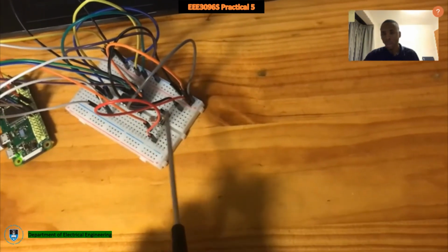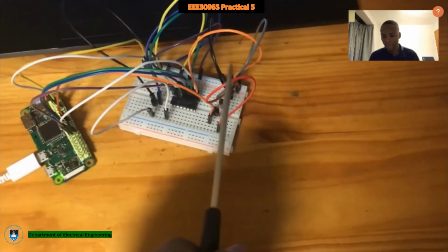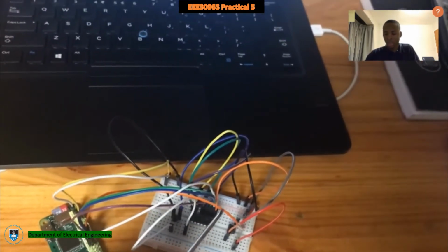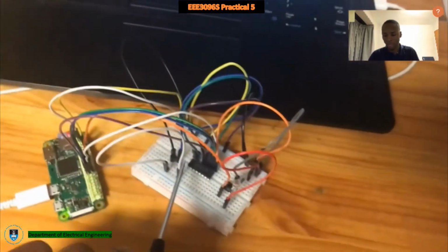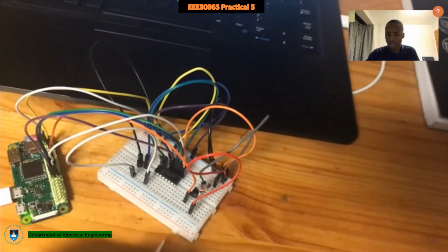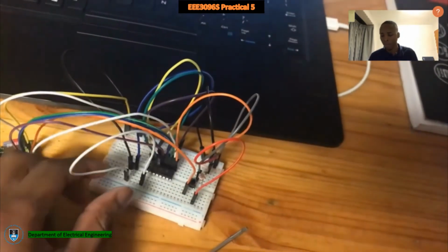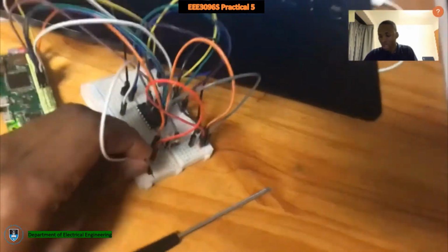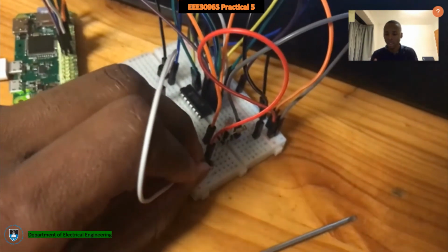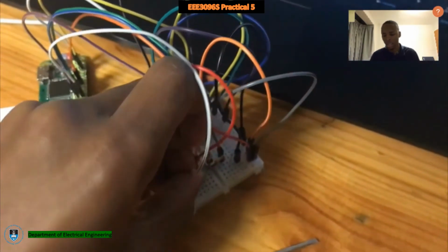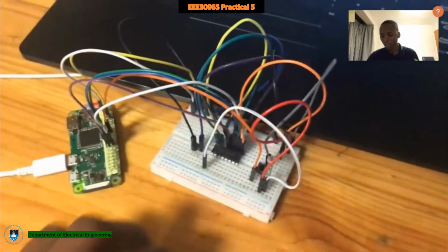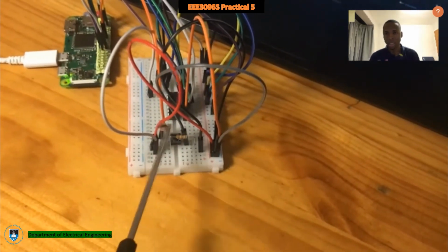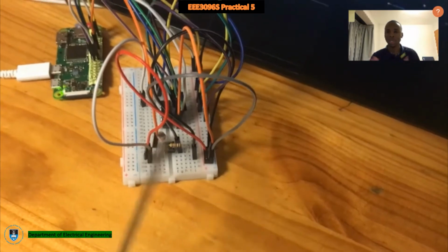Firstly, we'd like to work with our secondary circuit, which is connected to the actual circuit, and from there we can use channel 0, which is pin 1 of the ADC, to take readings from our thermistor. Right, so let's start off with using the LDR. If the LDR works as expected, then we can safely go to our MCP9700 and be comfortable believing that the results we get from the temperature reading is the actual temperature inside the building.